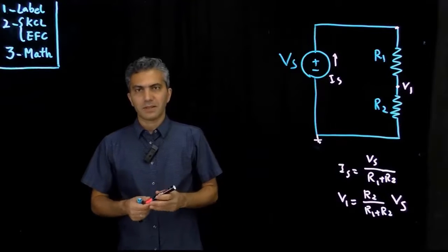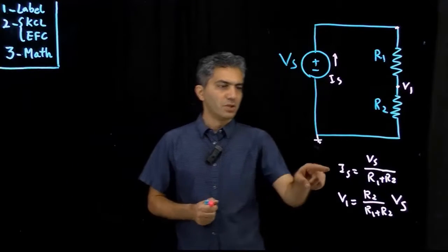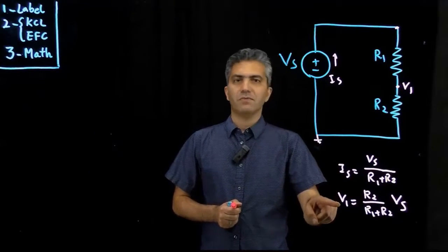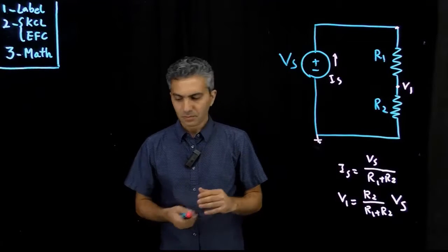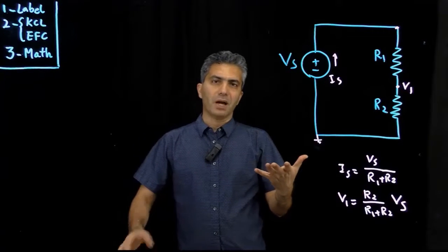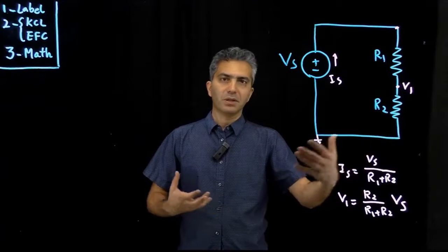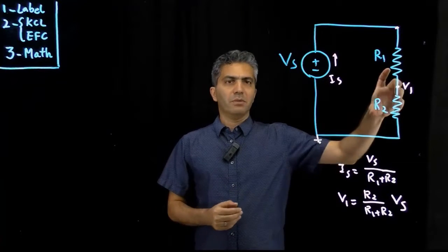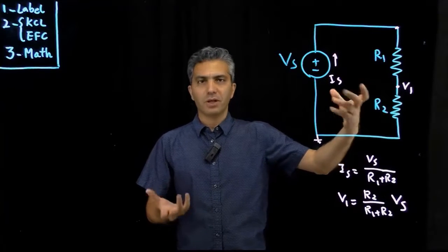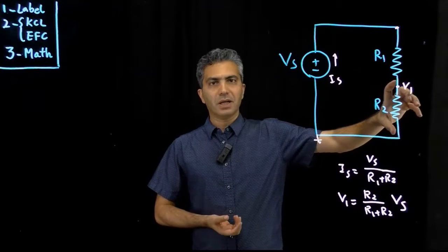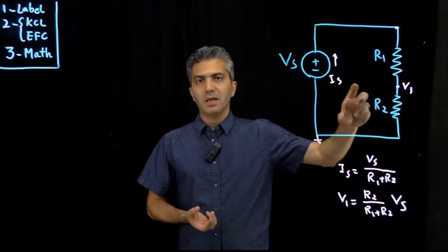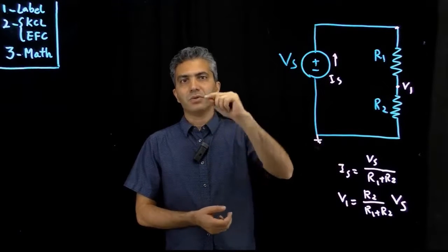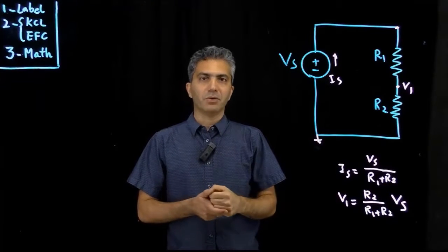Okay, so now let's say I want to measure this current or this voltage in the circuit. So the equipment that we have for that are called voltmeters and ammeters. For the voltage, any voltage is measured across two terminals, and a current is measured through two terminals.